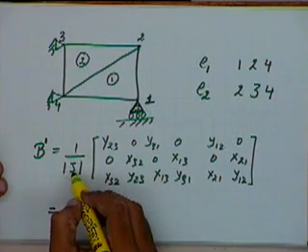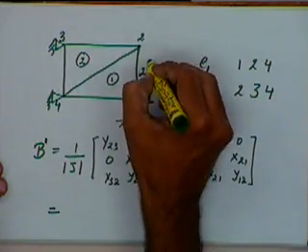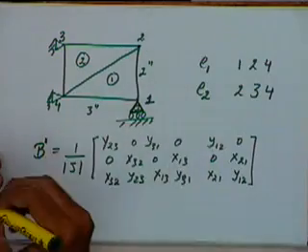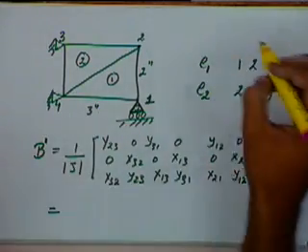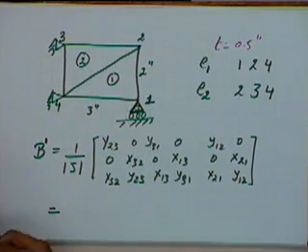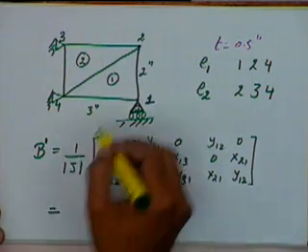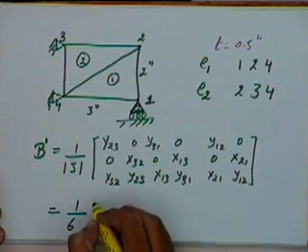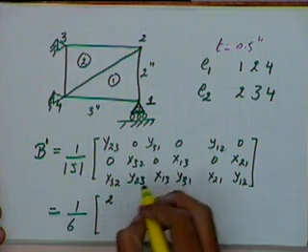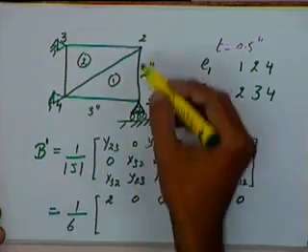I mentioned earlier that the determinant of the Jacobian will be 2 times the area of the element. So let us say if I take the sides, let us say this is 2 inches and this is 3 inches, and if I say the thickness T is equal to 0.5 inches, then the determinant of the Jacobian will be 6, and these values y23, I can get these values like this, y2 minus y3.